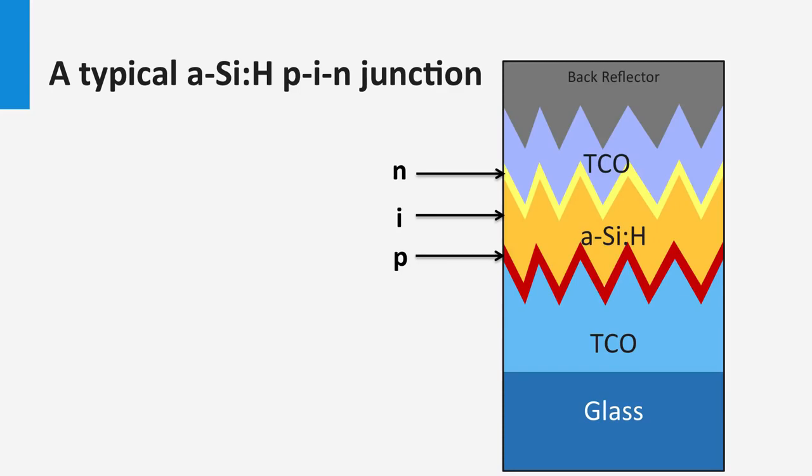P-doped layers are boron-doped amorphous silicon, but also the higher bandgap materials such as boron-doped silicon carbide and silicon oxide layers are used to enhance the transmission of the bluish light into the absorber layer. As back reflector, usually a TCO and metal back reflector is integrated into the device. Metals are either aluminum or the more expensive silver, which has a higher back reflection compared to aluminum.